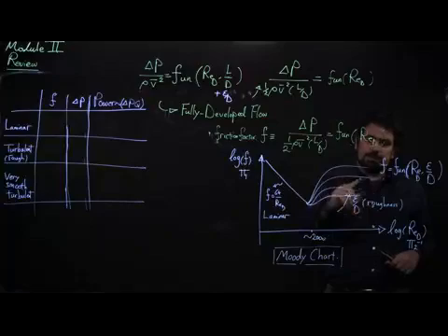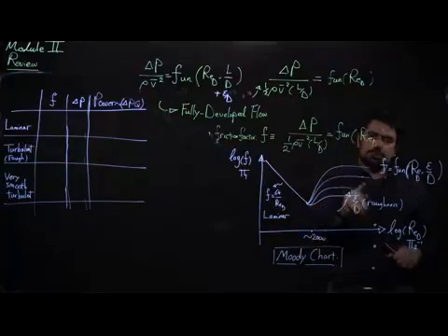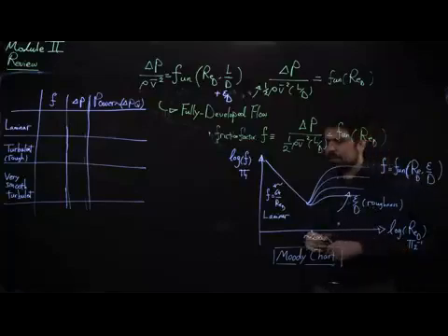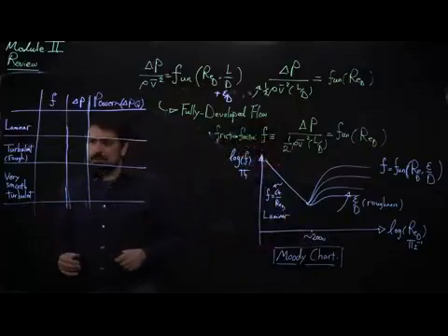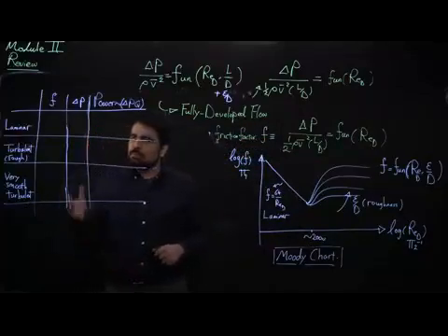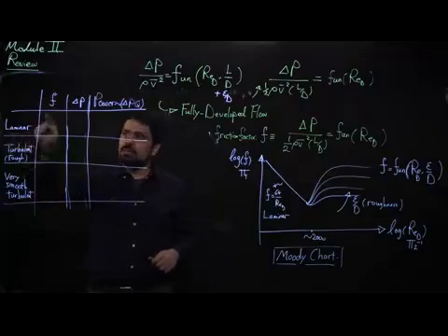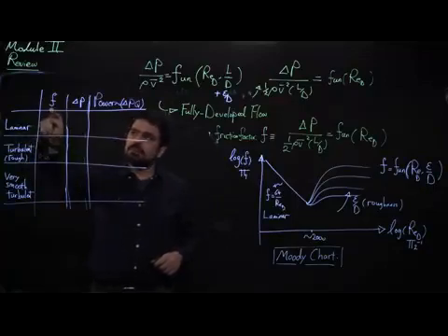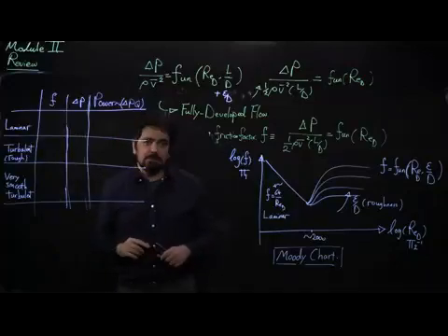For all these different roughnesses, one thing that happens, and is the same phenomenon in all of them, is the fact that at large enough Reynolds numbers, the friction factor becomes almost constant. Now, we can gather these ideas and tabulate them, as you have seen in the lectures before, in a table like this. We have a column that tells us what the friction factor is and how it scales with a parameter in this problem that we want to control.